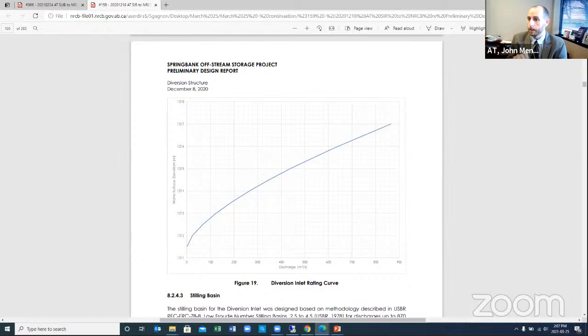And again, as I said, not a planned scenario, that would be a malfunction of the system, and we do not intend to push more than 600 down through it. But if it were to enter the channel, it would flow to the reservoir up until the point that the reservoir was completely full up to the emergency spillway, and then flows would discharge through the emergency spillway. And we've demonstrated that within our application.